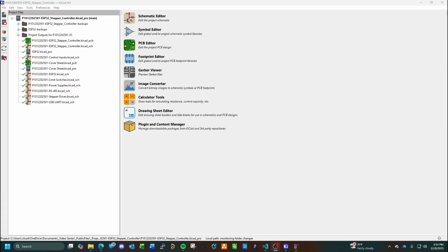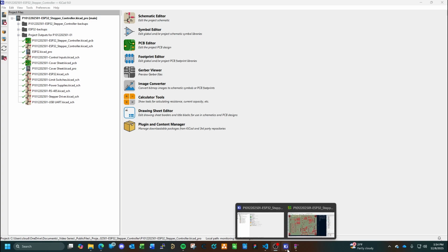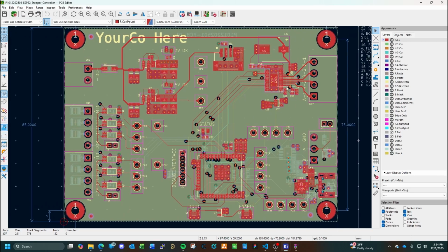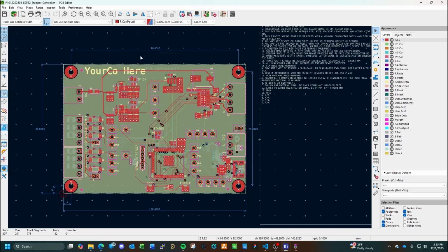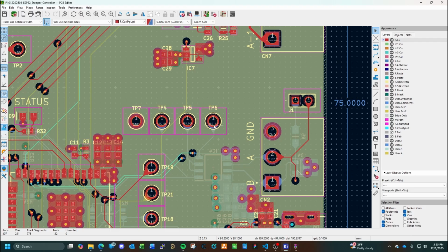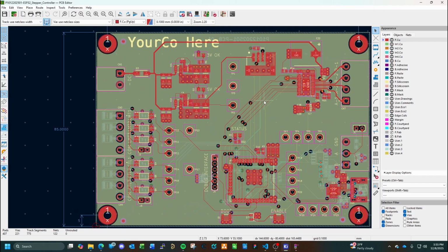So the last video, we went ahead and did as much verification of our PCB layout as we could within KiCad, just by looking at the design rules, running the design rule check, and fixing any issues, ignoring some, such as courtyard overlap, things that we can't immediately set rules to ignore, which is fine.